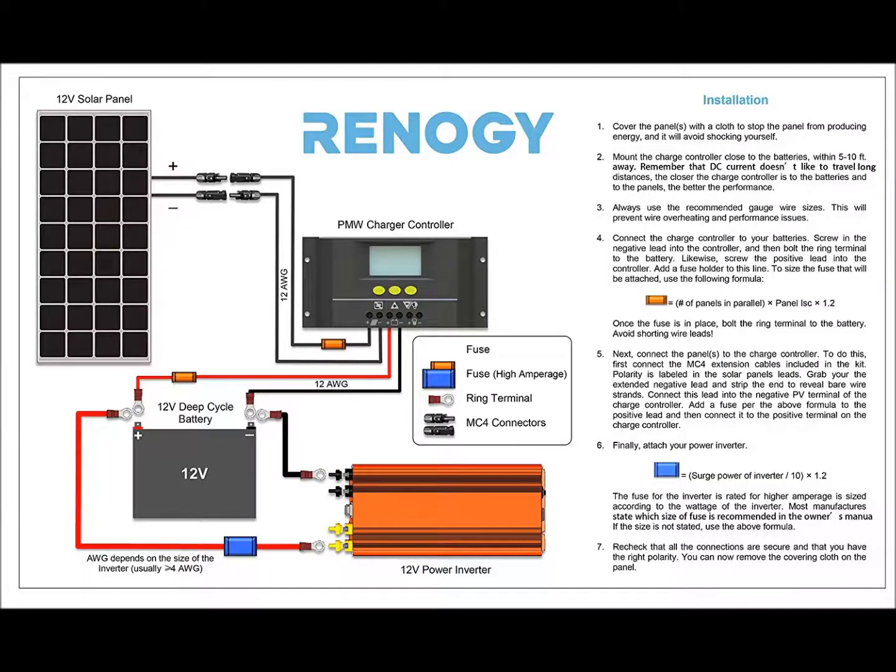Renewable energy solar systems typically come in voltages of 12 volts, 24 volts, and 48 volts, and can develop and store different amounts of power depending on the equipment. The charge controller limits the voltage and current being received by the batteries from the solar panels, usually with built-in fuses. The batteries then begin charging, and depending on the type of solar panel, you can get different voltage charges. An inverter rated to the voltage of the battery or batteries will then invert the incoming voltage into AC voltage, and depending on the inverter, you can run multiple wattage devices up to the inverter's rated wattage.